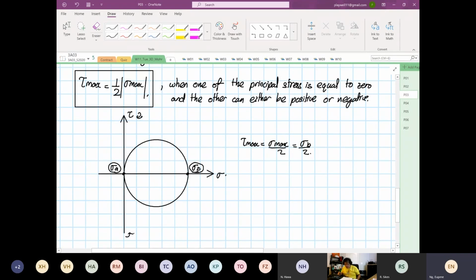So one thing I want you all to take note is stress A. So now when we use the criteria, you will see this quite often where stress A and stress B, not 1 and 2 anymore, are known as principal stresses. So i.e. the shear is equal to 0 at point A and point B.